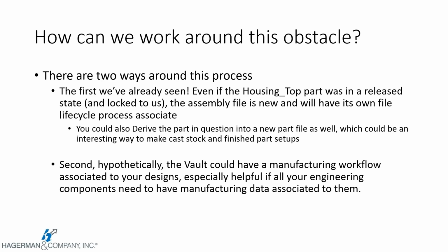The other way that we could do this would be to start up a new part file and derive in a component and use that derived component as one of my locked objects, right? I'm simply creating a parent-child relationship between the file I'm working in and that released document. The file I'm in is completely open to me. It's editable. I can make whatever changes I need to it and continue on. And this, again, is another really easy way to utilize a component and potentially model a stock around a component that exists, and then do whatever kind of edits I need to make to it as far as the CAM operations are concerned.